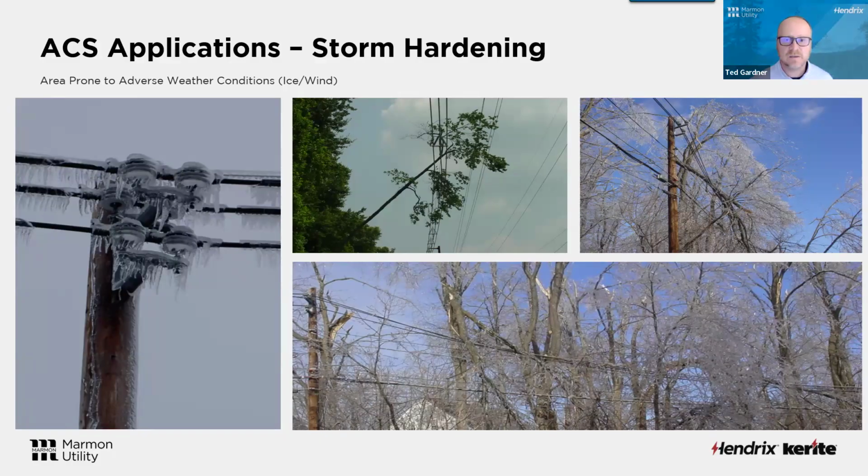One of the biggest mistakes that we see clients make is, their standard class 5, class 6 poles that they use for bare wire, and we're going to convert this line to spacer cable, and they use those same size poles. What you've done in those cases is you've moved the weak point of your system from the wire to the pole. And that's what we try to avoid. So again, that's where some of those design services and consulting that we can do, we can really help you with the pole loading and give you some idea of the sizes of poles and the ones that need replaced.